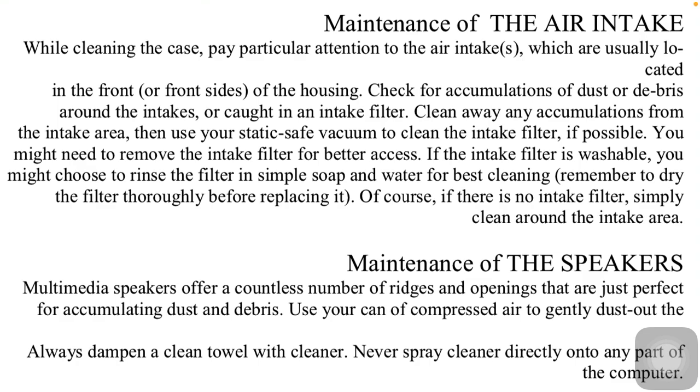There's a filter there, yes, but the filter can be blocked also. So clean all the dirt and accumulations so that air can easily go into it. There are some filters that are washable. Then remove it and wash simply with soap and water.